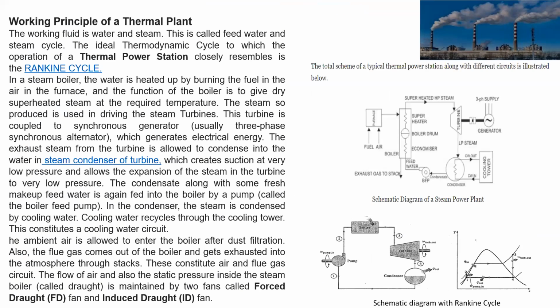In this last figure, just see the heater, economizer, and superheater, which I have not explained yet. When condensation takes place in the condenser, the water is taken to the boiler. Before that, this cold water, around 40 to 50 degrees Celsius, is heated with the help of some part of the steam taken from the turbine. So they are heated in the heaters, either low pressure or high pressure heaters. They are not shown, and that is not required for you also. By means of heating, the water gets warm, and that warm water is sent through the economizer.